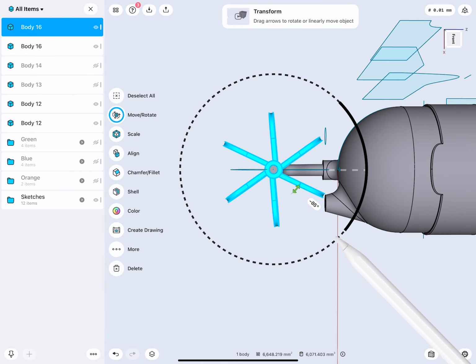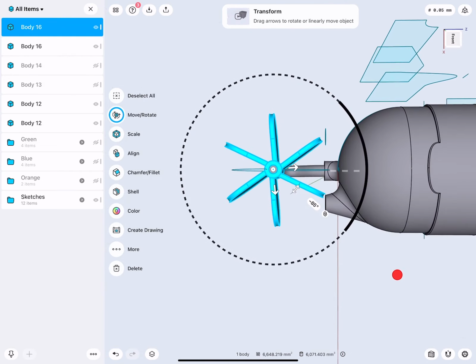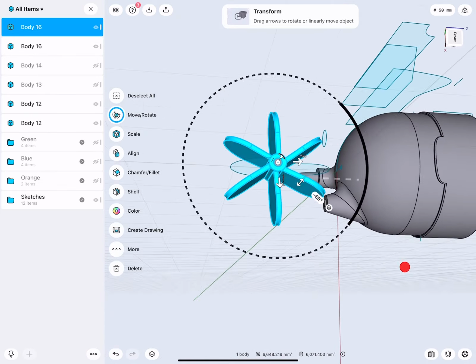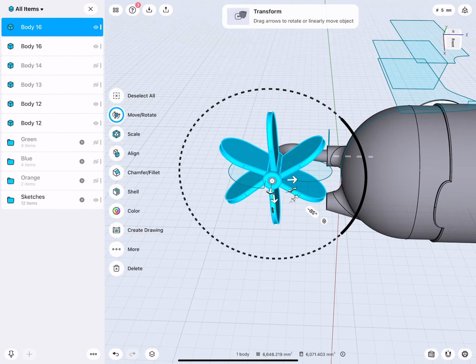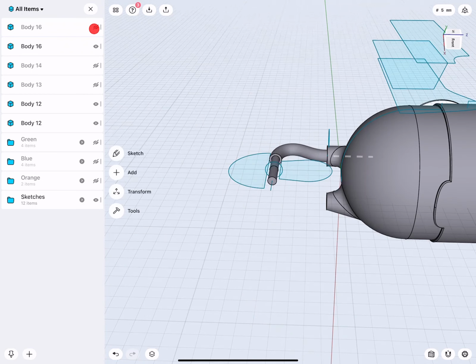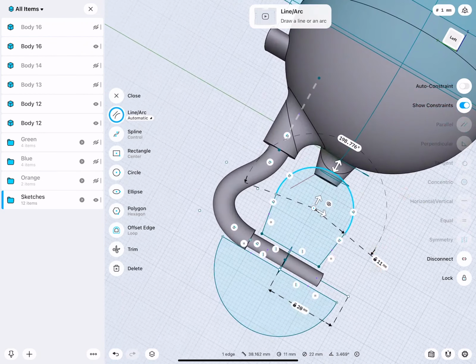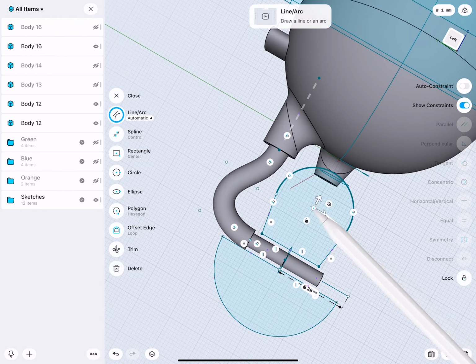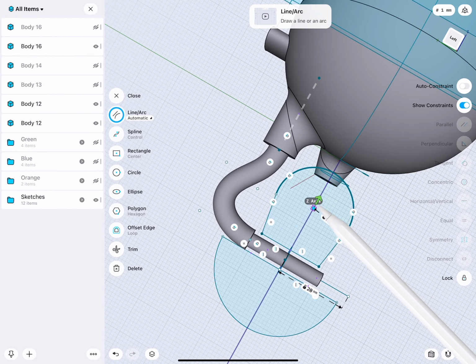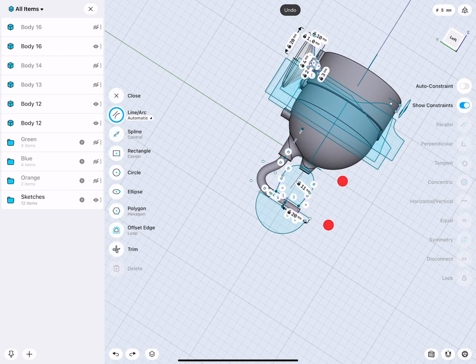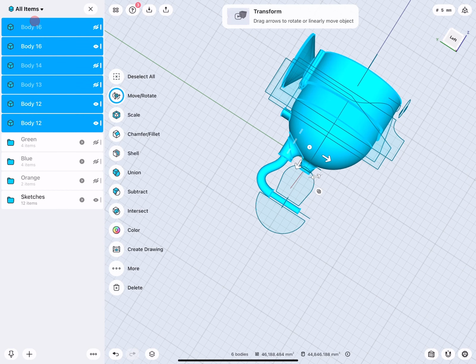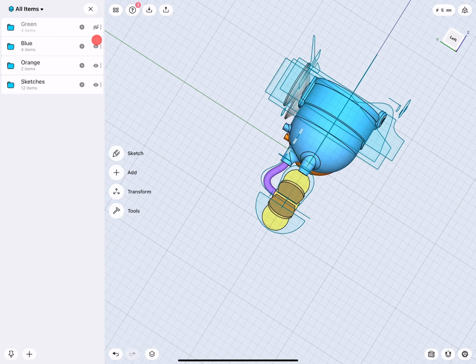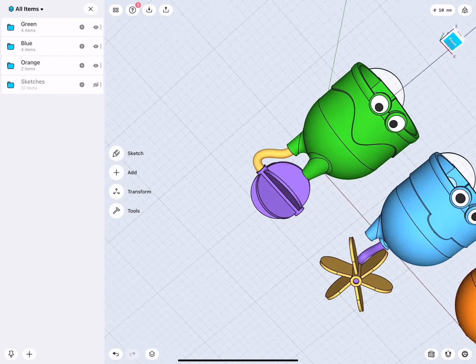This rotation tool is also really nice to see, is this okay? Is this a tick too tight? This is all good. If it's too tight, then we have to adjust the sketch. You see here I locked this line. Then the arc is tangent to these lines. The dimension is set for the radius. Then I could move this up and down and simply adjust the arc. Very good. Let me select all these elements and remove them and go back to this view.